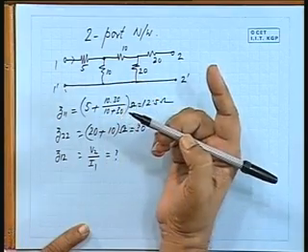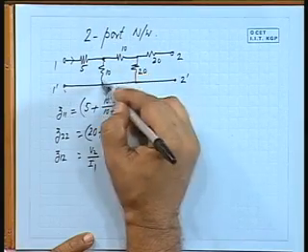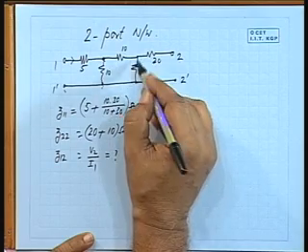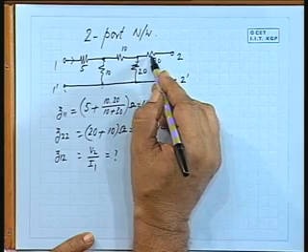Now in our earlier discussion, for a ladder network, it is something like a ladder structure. So if I have a unit current here, Z12 is V1 by I2. So I am sending in a current here. Say you can take 1 ampere here. If 1 ampere flows through this, that will give me 20 volts drop here. 20 by 20, 1 ampere here. So 1 plus 1, 2 amperes.